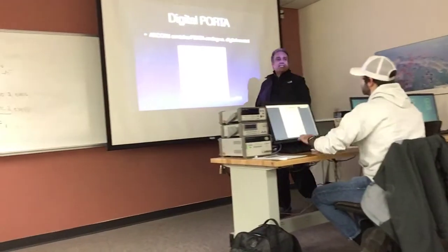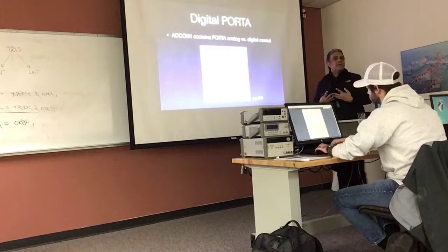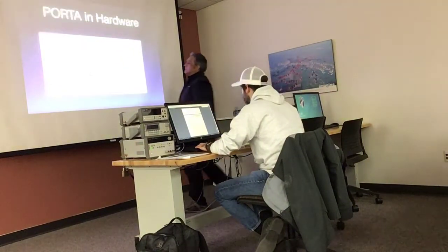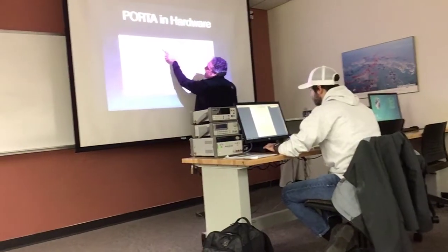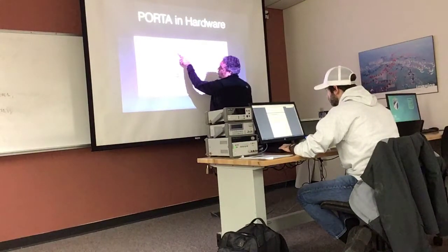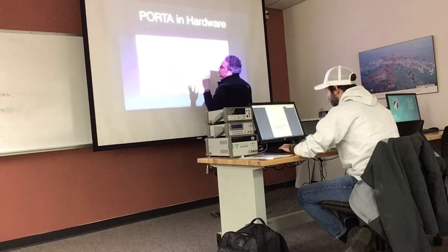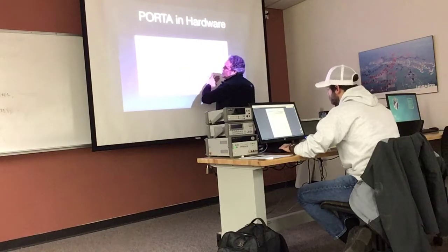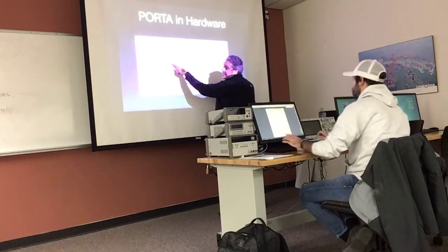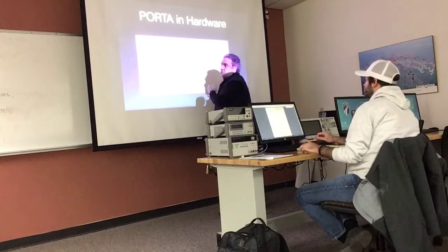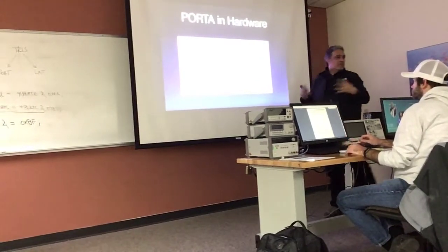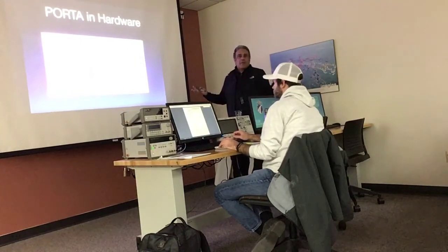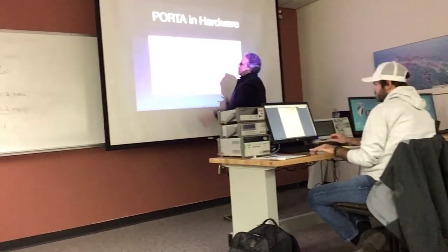That register contains the bits that are necessary for the behavior of port A. Okay? So, I'm going to go back to this. If you notice port A, I have AN0, AN1, 2, 3, and 4 as part of port A. Notice that AN5, 6, and 7 are not in port A. They're on port E. See that? So, we just have to contend. It doesn't make any logical sense now, but this is what they did, and we just have to follow what they did.